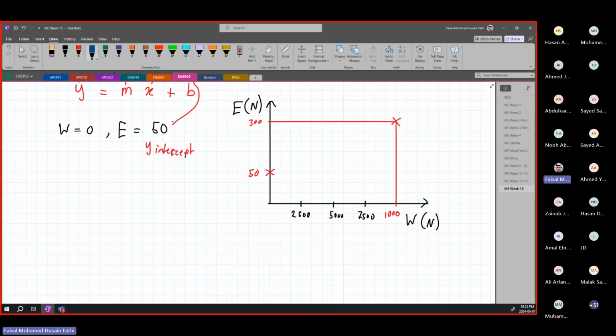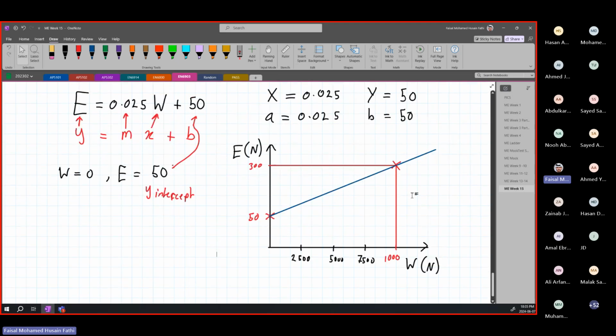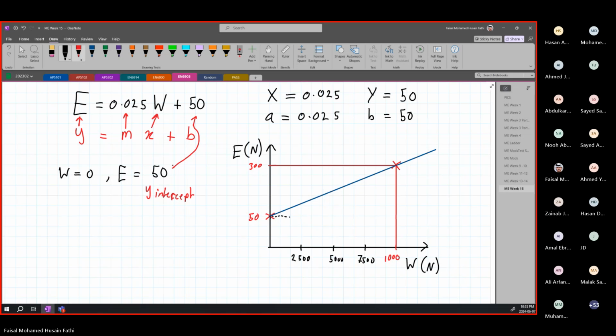And that's it. And then you will just draw a line between your 2 points, and that is your line of machine. It will always be a positive slope, and it will always look something like this. It will always start above the 0 line on the y-axis, and this is your law of machine. All right. An additional thing you need to know is you will always have a slope, and you can write your slope over here as the value of m. This is your slope.